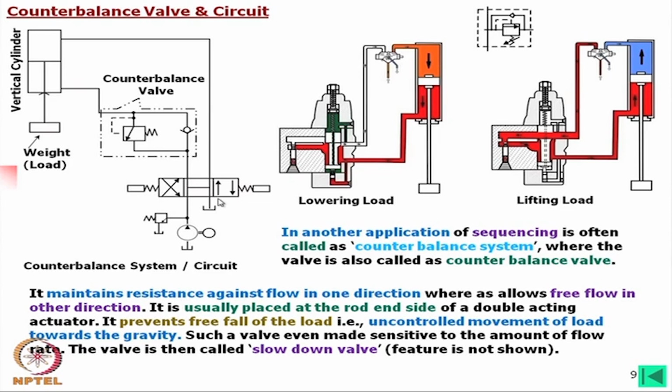So, this side is connected to the tank and the pump side, or pressure side, is connected the other way. Now, while this load is being lowered, how much pressure do we need? Practically we do not need the pressure. What we need is the flow, because this is to be filled, otherwise it will not move.